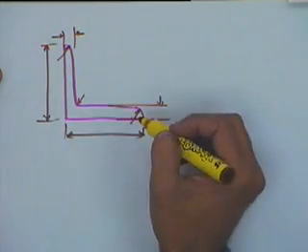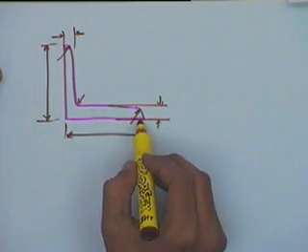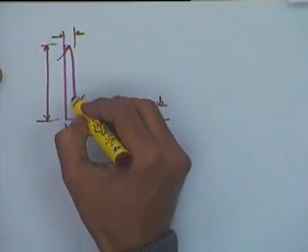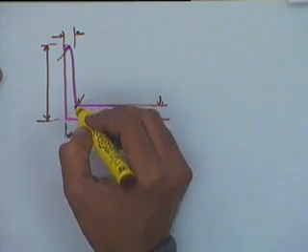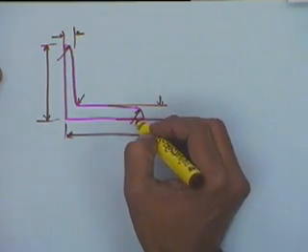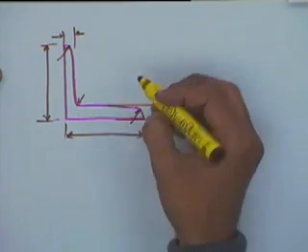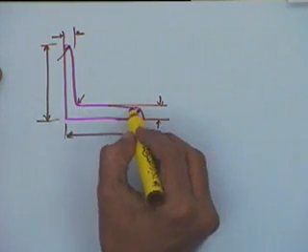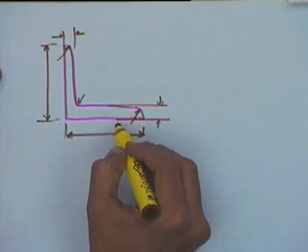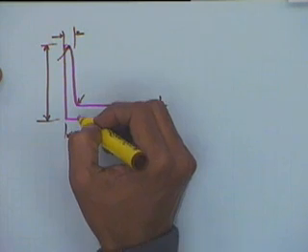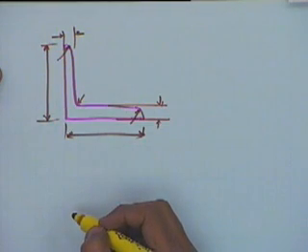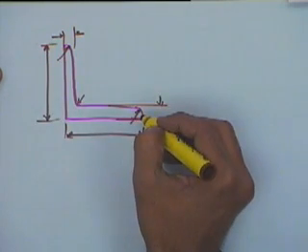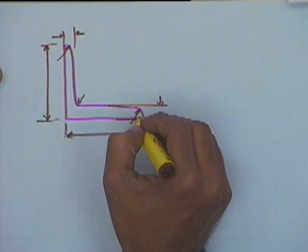Making an angle like this would mean that I'll first take a horizontal plate, a vertical plate. I'll take the union, then I'll take a fillet over here. Then maybe I'll take another fillet here, another fillet here, and so on. Plus this angle can also have a draft over here. That will complicate matters even further. Every time I have to make an angle, one would normally not like to go through a sequence of steps like that. So what is often done is we make primitives which are complex objects like this.